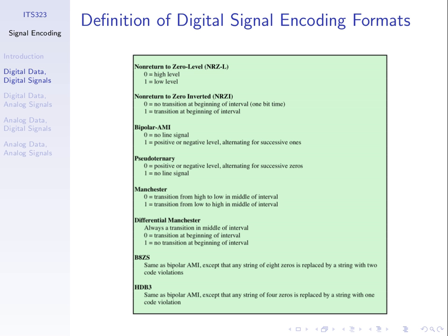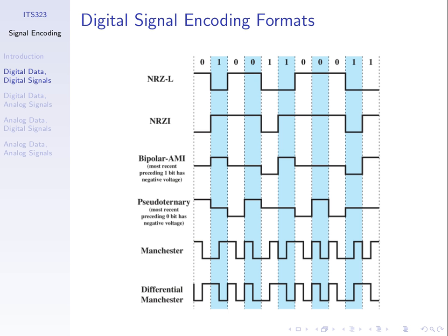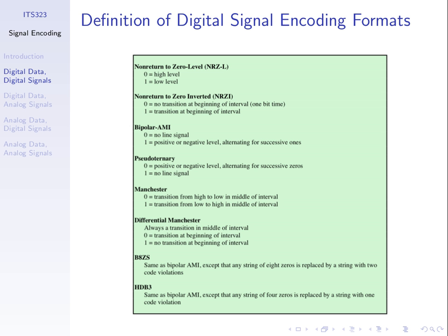So this is non-return to 0 invert on 1s. Did I get it correct? That's this second example here. So a different signal encoding scheme where the digital signal is we maintain a level if we want to transmit a bit 0, and we invert or perform a transition if we want to transmit a bit 1. Non-return to 0, we do not send at 0 volts, we go between a negative and a positive voltage, doesn't matter the values. Inverted, meaning we invert on 1s, on bit 1s.